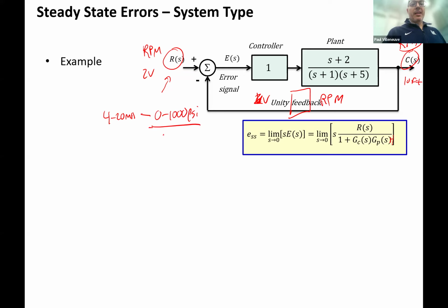is you divide this by a number, and this becomes engineering units. Everything is a ratio between 0 and 1. So the speed or the water level or the pressure is all between a range of 0 and 1. So the input is between 0 and 1, and you can compare the output between 0 and 1. So you do everything in what are called engineering units, then you don't have to worry about any of this feedback stuff. It all happens to be on the same scale.